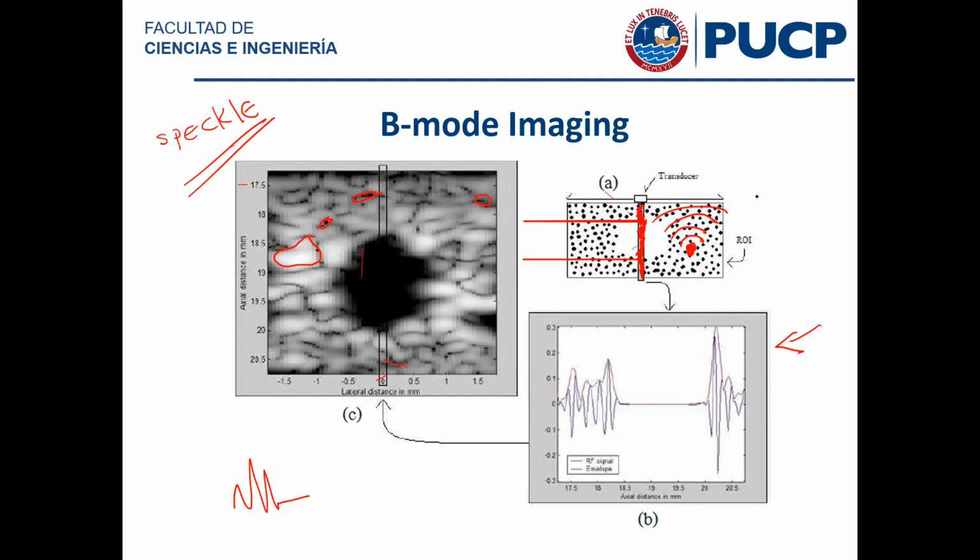Okay, so what we're watching in the B mode image is a 2D graphic of all the envelopes, with the width of the tiny piezoelectric that is used. When you place a piezoelectric in one location, you get one set of echoes, like one panel B. Then you take the envelope and calculate the logarithm, so you make this into a logarithmic or decibel scale, and bring that into one column of the image.